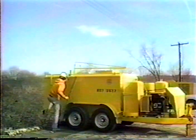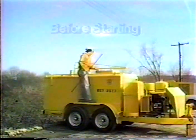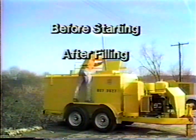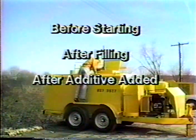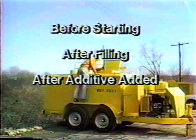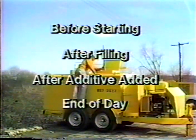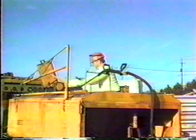The final step in preparation is to determine the amount of sealant in the kettle before starting, after filling to determine the amount of additive required, and after the addition of the additive. This is done using a dipstick calibrated for the kettle being used. Another reading will be required at the end of the day to determine the day's production. When an additive is used, the proper amount must be determined from the amount of asphalt cement added.